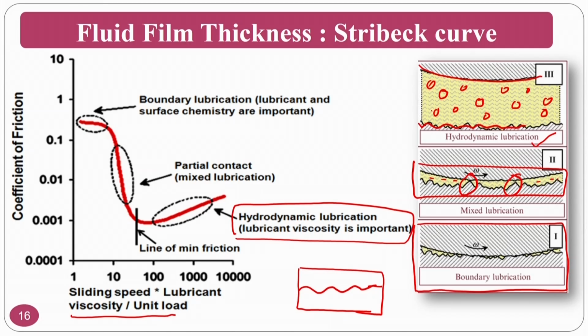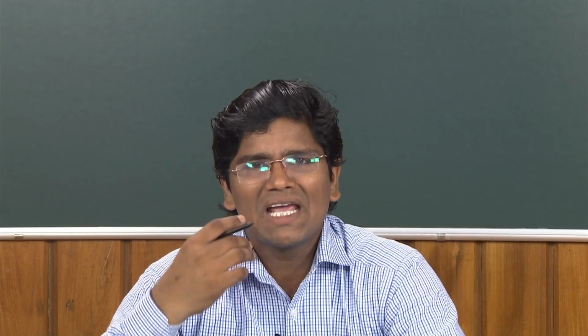This hydrodynamic lubrication zone is what you use in elastic emission machining. Because of the rotational effect of your tool as well as the normal load, your abrasive particles are guided and chemically react with the workpiece, forming a layer, and material removal takes place.